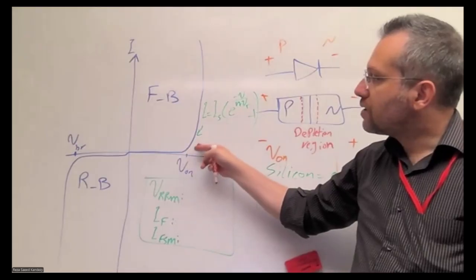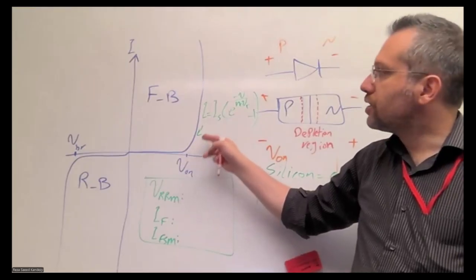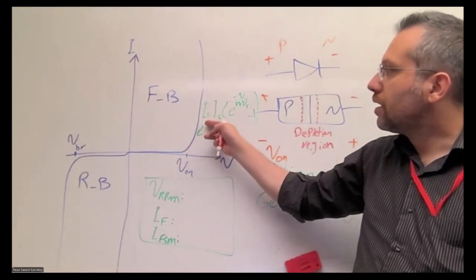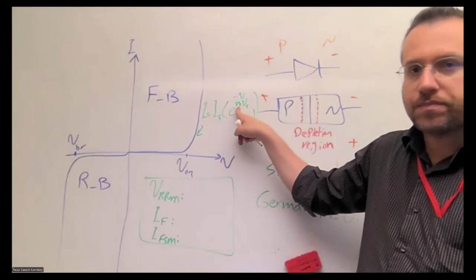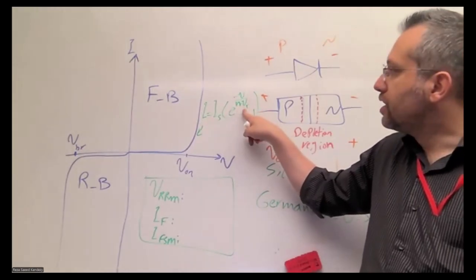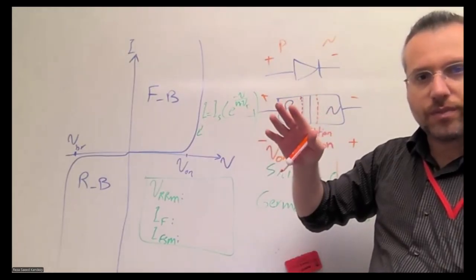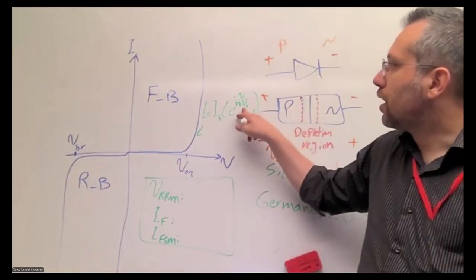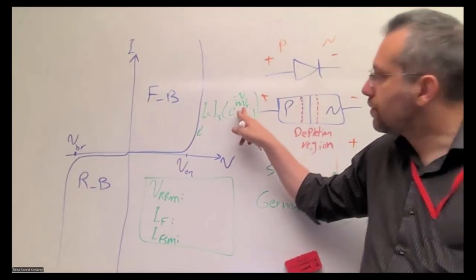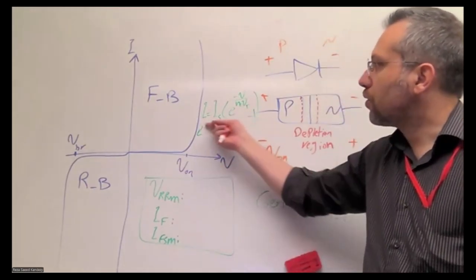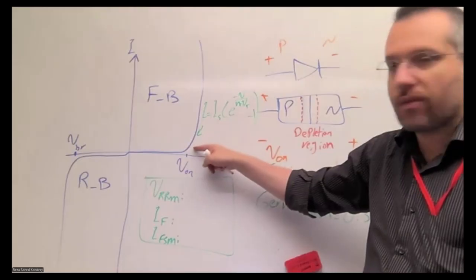Okay, we have some sort of exponential function that defines the relationship of the current and the voltage. Now, this N is the ideality factor, defined in the datasheet. And this VT is the thermal voltage, normally 26 millivolts, and it's also included in the datasheet of the diodes. And this is the actual real relation between the current and voltage, the function of this exponential curve.